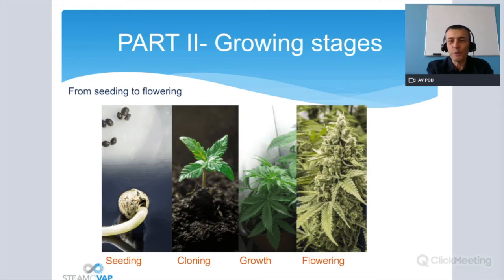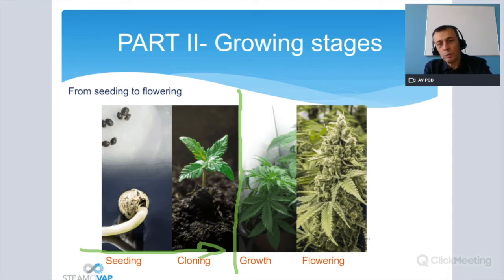So I cannot ask you in the webinar, which part of the process do you think requires the most humidity? And you have probably heard in the past, some people will tell you that, oh, marijuana, you don't need humidity because the plants are producing too much humidity. You have to get rid of the humidity. You need a dehumidifier, not a humidifier. This is wrong. In fact, it depends on which stage. And I will draw a line, and this line is where you will need to bring humidity and where you will probably have too much humidity, at some times of the day.